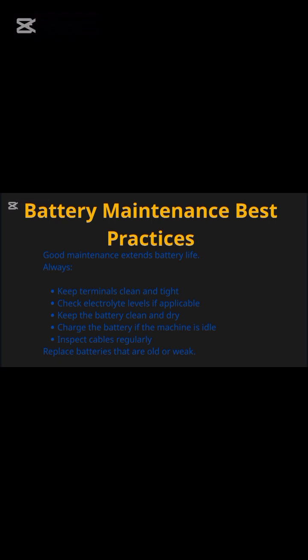Keep the battery clean and dry. 4. Charge the battery if the machine is idle. 5. Inspect cables regularly. Replace batteries that are old or weak.